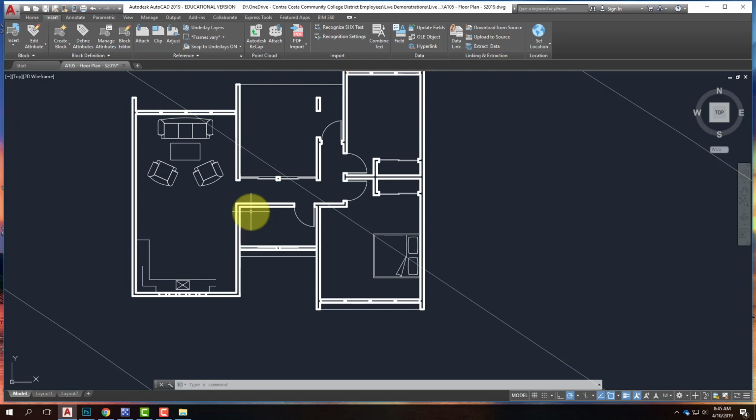Brooke, you had a question. Is there a difference between putting something on a layer from the drop down while you're doing the layers, and then putting it on the property layer? No, if you have the properties window, I haven't opened the properties window yet. If you change the layer in the properties window, it's exactly the same. Yep, it'll do the exact same thing. We will come to the properties menu. I think in 2 classes I'll start talking about the properties menu. But if you feel more comfortable changing the layer in the properties window, that's perfectly fine.